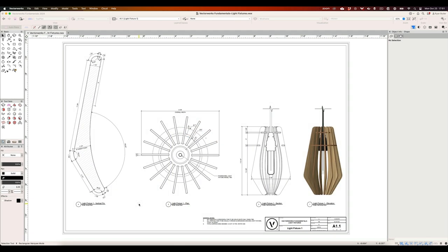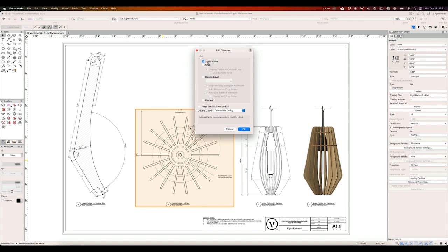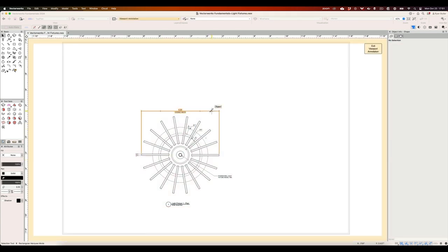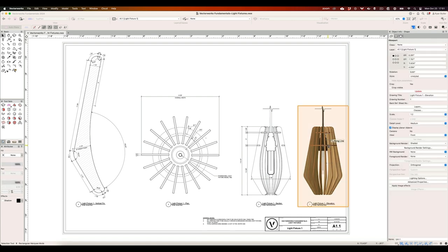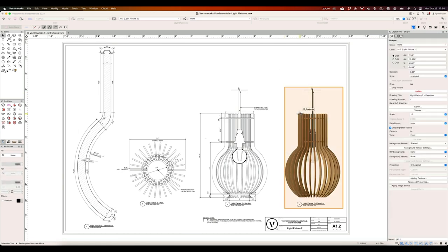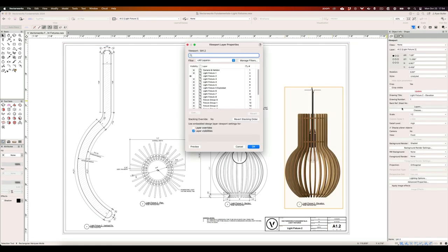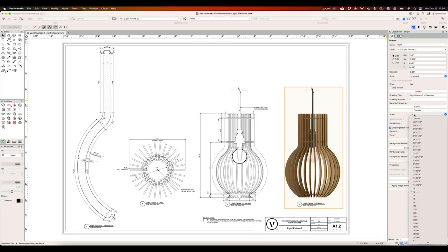So now to create some drawings from this model. I first created sheets and then created viewports of the light fixture, like in top plan view, elevation, section, and an elevation of the vertical piece itself. Each viewport has dimensions and notes drawn in the annotations of each viewport, and in the object info palette, there are settings you can change, like the background render, to hidden line, shaded, wireframe, or other render modes. For each viewport, there are also settings that can be adjusted in the object info palette, like scale, viewport crop, drawing title and number, layer and class visibilities, and so on.